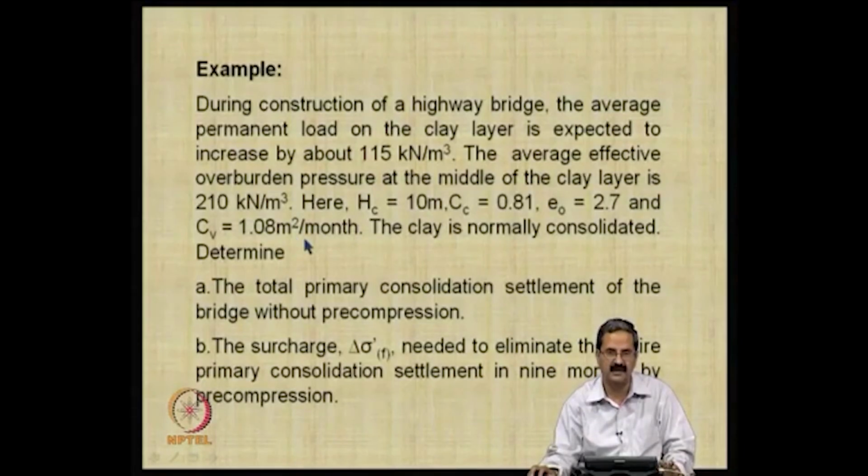We are trying to discuss in terms of months because you have to convert what you get in the laboratory, which is normally in seconds or minutes, to months, because we are more comfortable with construction times. So, we will try to calculate the total primary consolidation settlement without pre-compression and how much surcharge you need to apply.